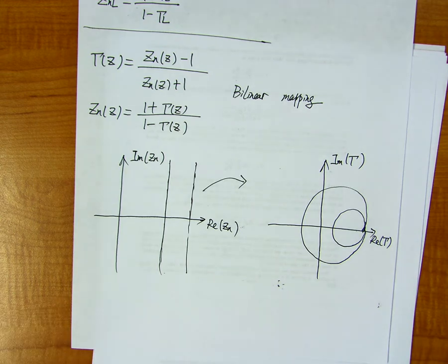You can read in the lecture notes that the Smith chart is very convenient when you want to do, for example, impedance matching, or if you have a transmission line connected to a load and you want to calculate the reflection coefficient. Yes? I think that point is 3 plus j3. Oh yeah, 2 plus j3, sorry. 2 plus j3, where this horizontal axis represents the real part of your impedance, and these numbers on the outer circle represent the imaginary part of your impedance.